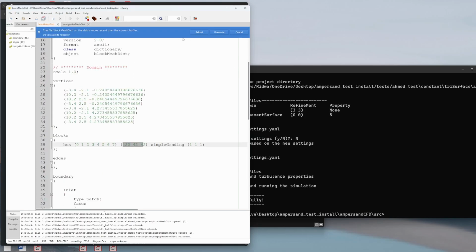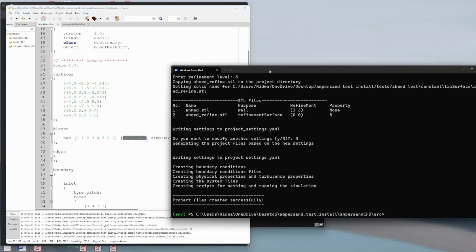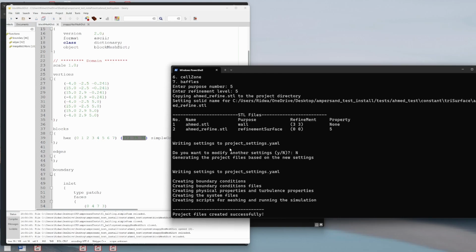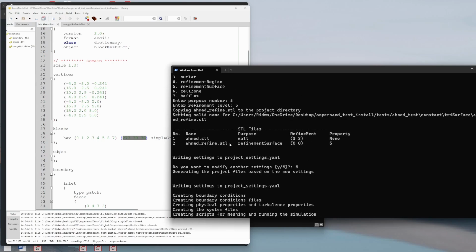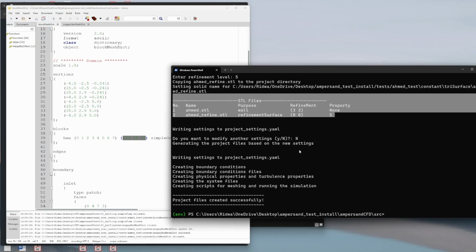Okay, and also blockMesh is changed, and here the new coordinates I've given are already set, and the new mesh size is changed. So if you run this, you will have a much finer mesh, because I increased these things a lot. And finally, if you change something and you don't remember what you did, you can see this summary a little bit, and I'm going to improve this for more complex solvers and more complex physics. So please stay tuned.